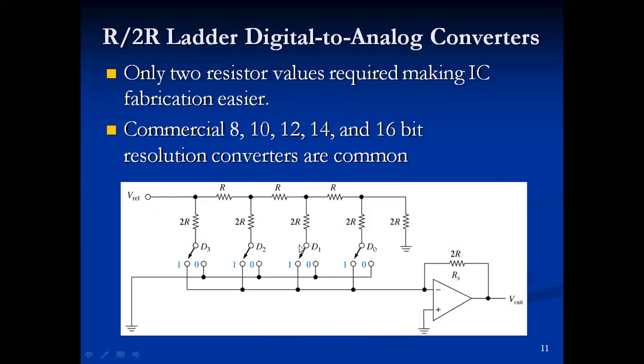And if I change the closed switch to D1 and open D0, again, I'm going to have the current flowing through these resistors down through 2R into the node here. But look, I have actually only gone through 2 sets of resistors instead of 3. So I've reduced the number of resistors that I go through, which will increase the amount of current through this resistor here.